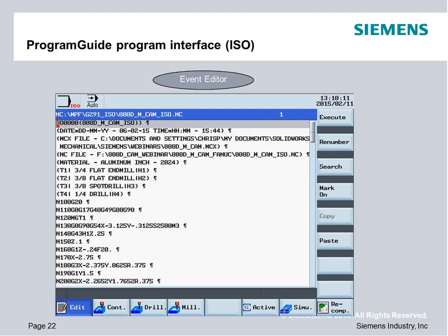Then we're going to go in and we're going to look at the part program. And for those of you that are experienced with ISO or Fanuc style programs, you're going to see this is really posted directly for a Fanuc machine. No editing needed per se, just no percent signs, and you want to just comment out the program number. You don't need the program number. Other than that, it's a direct drag and drop into the system.